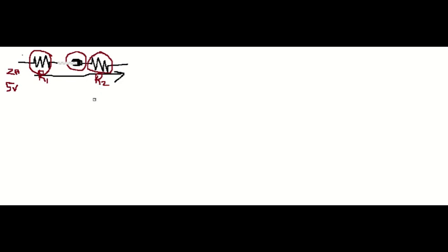Now let us quickly look at the formula used to calculate resistors in series. So we have total resistance, RT, and please note that the T is smaller than the R, so the T is a subscript, which is equal to R1 plus R2 plus R3, and we can add as many resistors as needed, right? So the N represents any number or the amount of resistors that we need to add.